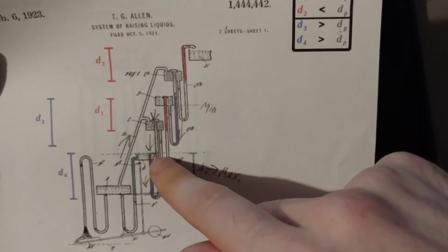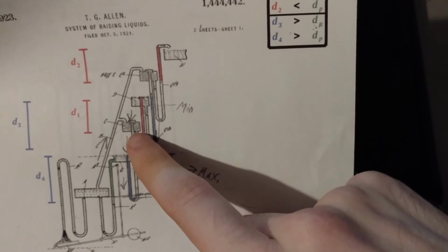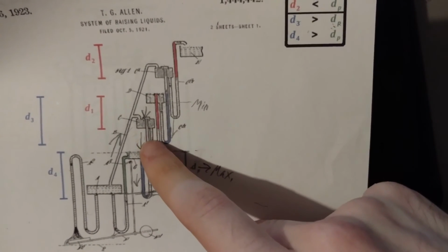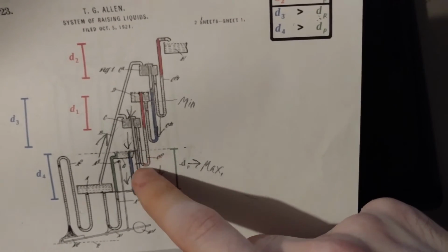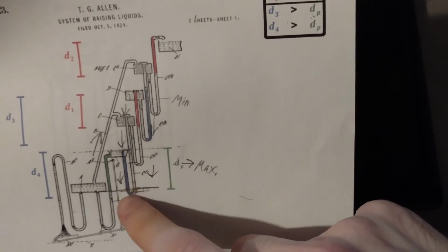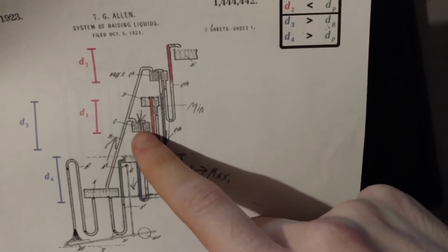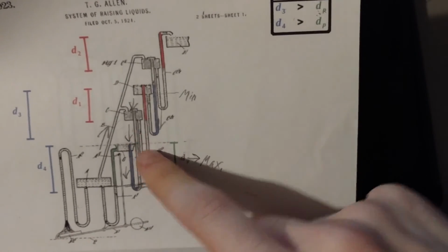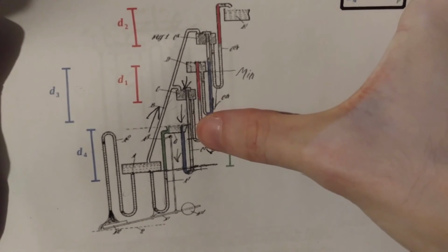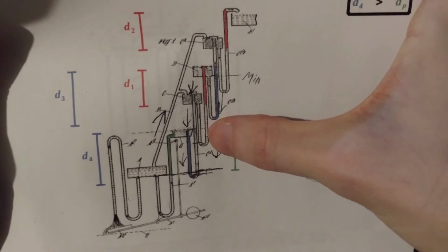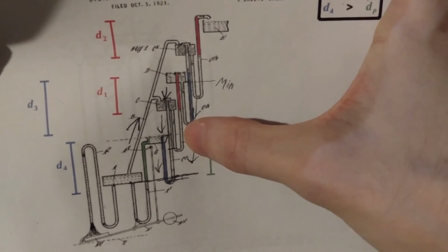So the air being pushed into this tube here, if there's too much, the first place it's going to go is as it's being pushed down past that bottom there. If you have so much pressure, it's going to go down, and the first place it's going to loop through. I mean, if you have an incredible amount of pressure, it'll go into this tube as well. But you don't want it to get to that point first off. So anyways, the air pressure will be pushed down the tube here right next to my thumb, the output tube. You want to make sure that that air does not get past that U, doesn't get past that trap.